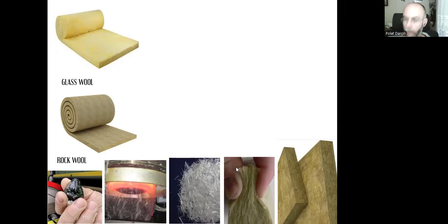If they get wet, all these gaps between these fibers will be filled with water, and they will get very heavy, like when you are washing your carpets. The dry carpets, you can hold them, you can carry them, but as the carpets get wet, they become very heavy because they hold lots of water. And since the gaps are filled with water now, they start to transfer the heat quicker. So we don't want them wet. We need to keep them away from water.